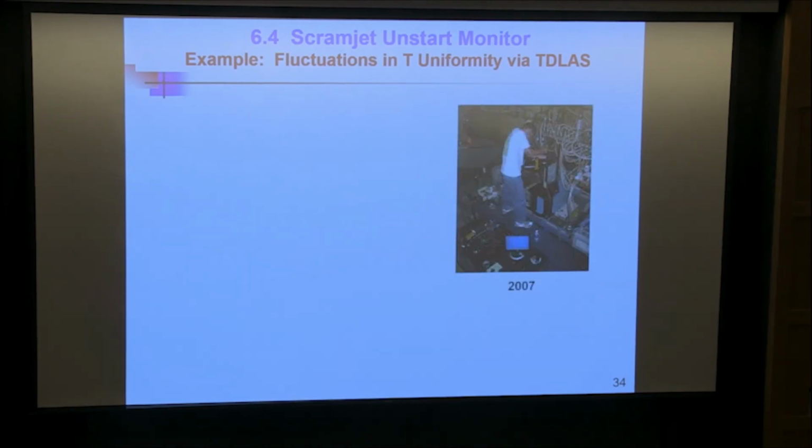Okay, now we're going to go to Wright-Patterson Air Force Base, 15 years ago, I forget. That's Greg Grieker. He went once or twice. I think they call it Tunnel 19 at Wright-Patterson. So it's a big, vitiated combustion tunnel to test scramjets. The heated gas expands through a nozzle, and then they flow the gas through the combustor, introduce the fuel, and see how well it burns and how it mixes. So they want to measure how well it combusts.